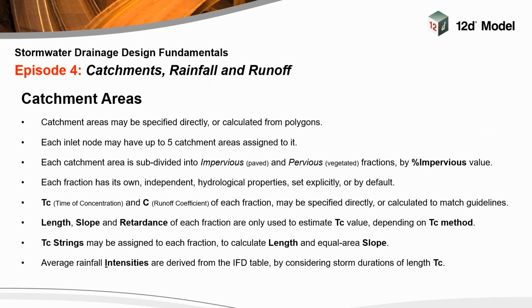But we do want to talk about catchment areas. It is a big part of this webinar today. And when we talk about catchment areas, they don't have to be done from polygons, but they normally are. They can be specified either directly in hectares, or you can calculate them from polygons. Get 12D to calculate the area by drawing polygons.